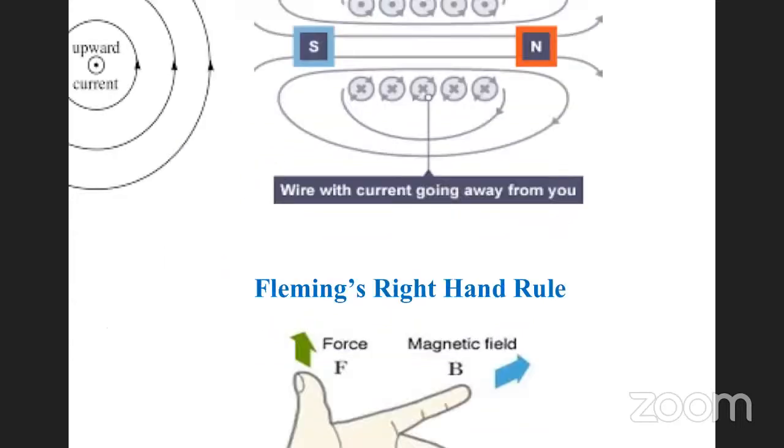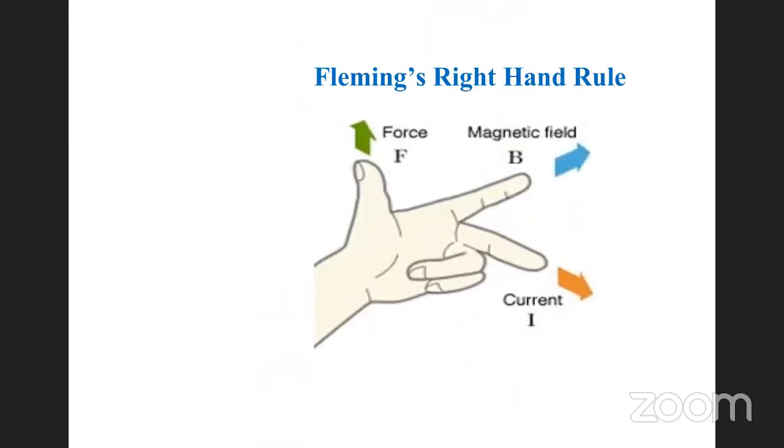Here's the next example of what we're talking about. If I were to take a magnetic field, north to south, and put a current carrying conductor inside it, based on what we learned earlier, we should experience a force. Remember we said two north poles will repel, north and south attract. Same principle here. Because the current carrying conductor has a magnetic field and the magnet has a magnetic field, a force will be experienced. How are we going to figure out the force?